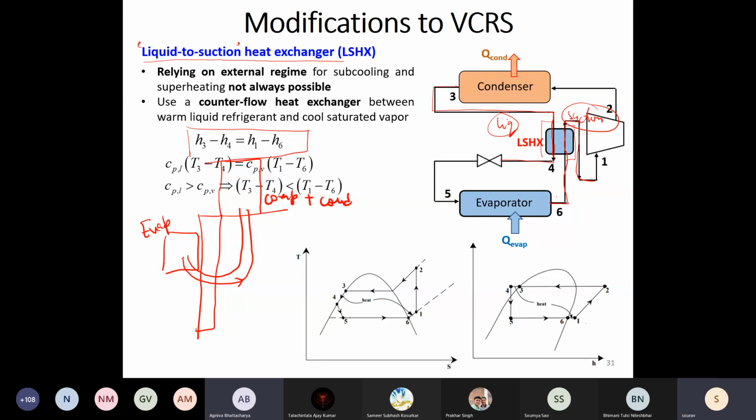So this line which comes out of the evaporator, that is the indoor unit, and goes to the compressor, is the suction line. And the other line which comes in to your evaporator, since your indoor unit also has the throttling device placed somewhere here, so your indoor unit has the evaporator and the throttling device. This line which comes here is the liquid line.